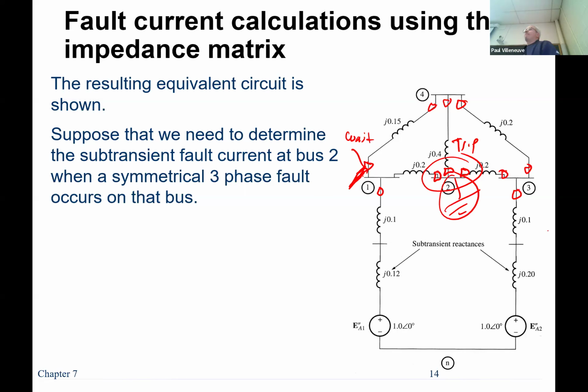Why didn't you put the second time? Because without getting into a lot of detail, you have a CT in here and you have a ground screw here and a ground screw here. What was happening is there was supposed to be current going through a differential element here and a comparison on this side.